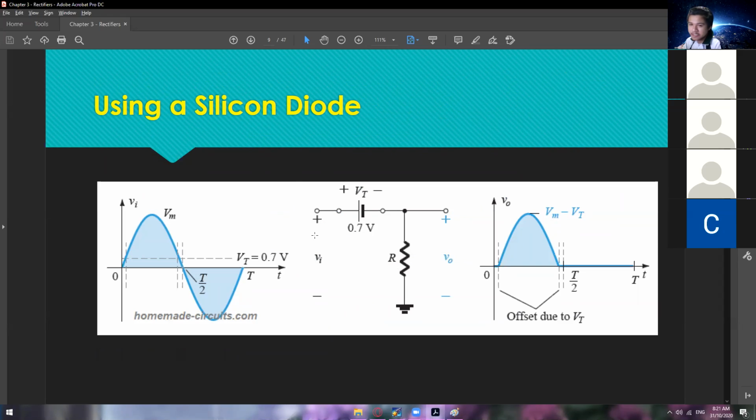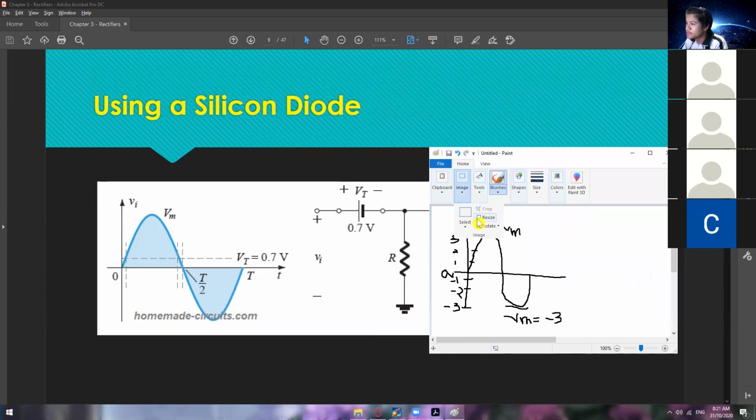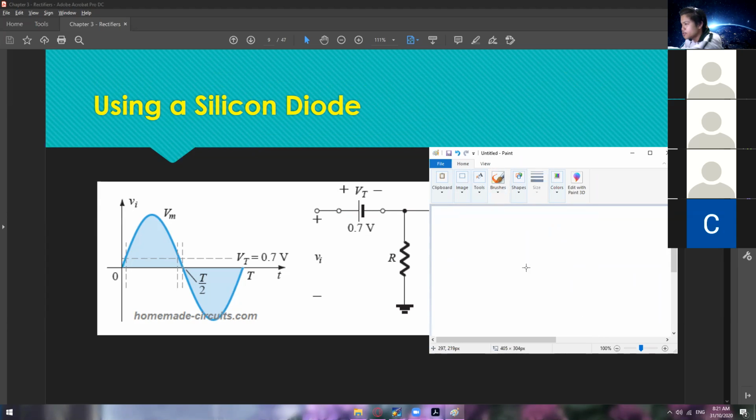So before, we've considered that as an ideal diode, meaning it could be just a normal switch, an open or a closed circuit. But in here, we now have to consider the voltage threshold of the diode. So if you take a look at this one, you have to cut this part, since our diode will eat 0.7 volt first before conducting a voltage at this point. So if I draw a more precise graph of this one, then we will have this one.